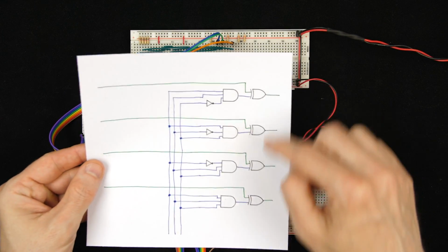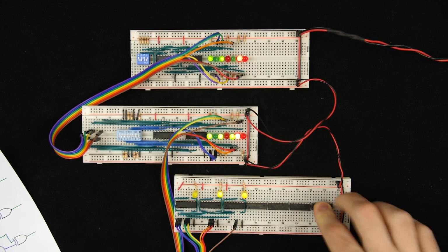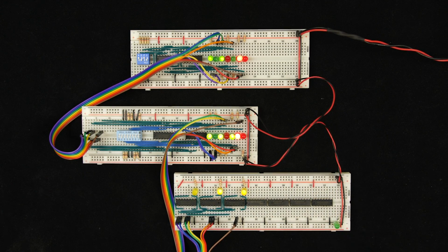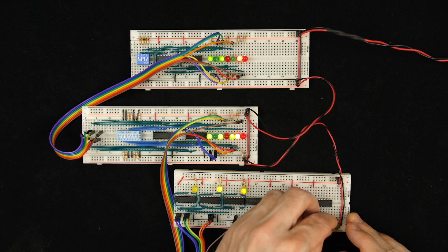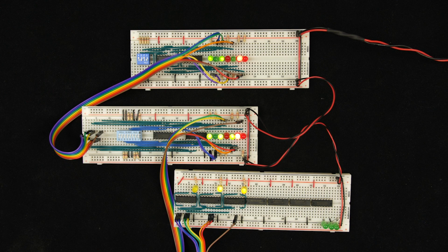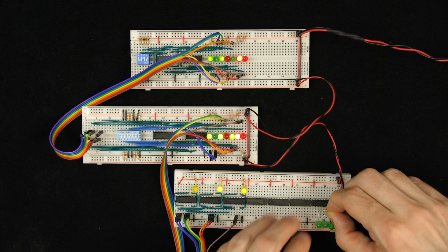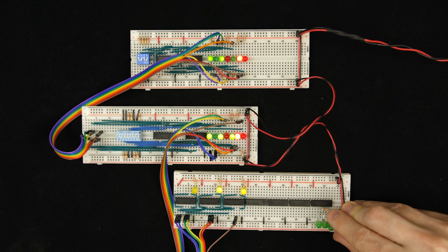And then finally, more XOR gates, so the 74LS86 again. So go ahead and power all these up. And then finally, the output here, I just want to hook up some LEDs. And it's getting pretty tight over here on the edge of this breadboard, but I think I can squeeze in 4 LEDs just to be able to see the 4 data bits that we started with. And then connect each one up to the 4 different outputs of the 74LS86.